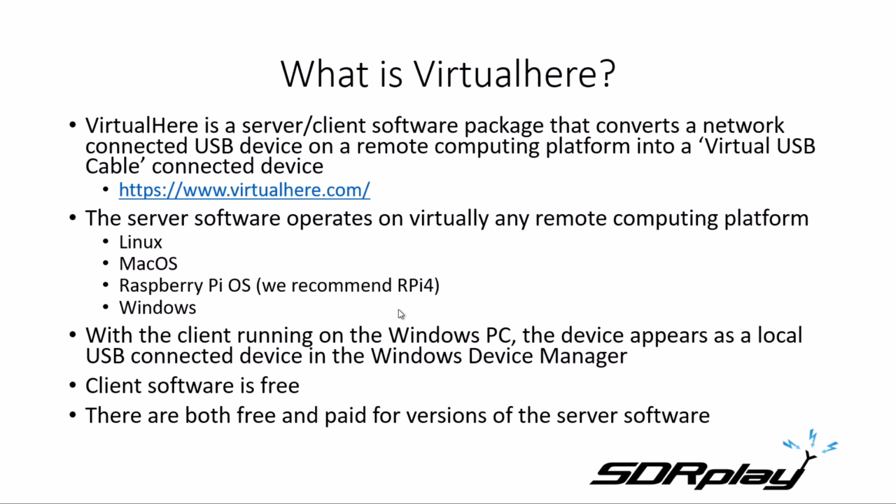The server can be any platform, Linux, Mac, Windows for x86 hardware, and then for ARM processors you've got things like the Raspberry Pi and Odroid. We're looking at the Raspberry Pi 4 specifically. Those of you that have watched previous videos and webinars that we've done where we've talked about small board computers before, remember that on the previous generation of the Raspberry Pis, the 2 and 3, the bandwidth is shared between the USB system and the Ethernet system. So the sort of data rates that we're talking about here would probably not be suitable for a Raspberry Pi 2 or 3.